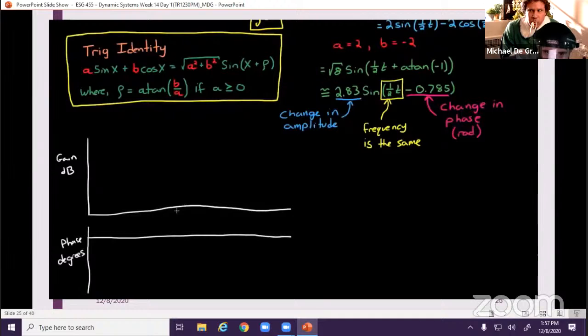The Bode plot allows frequency response information to be displayed graphically on 2 separate plots, one for gain and one for phase, both of which are plotted against frequency on a logarithmic horizontal axis. But there's a caveat to plotting amplitude gain on a Bode diagram. We don't just plot the magnitude of the gain directly. First, we have to convert it into power, and then we represent the power gain in decibels, which is a logarithmic unit. To convert the amplitude to decibels, you first take the log base 10 of the ratio of amplitudes and then multiply it by 20.